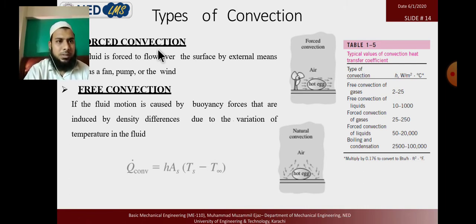Both have different pros and cons. In natural convection flow, we have less energy consumption, because there will be no fan, so the flow of the air is totally free and natural. But in forced convection, the fan is installed in the fridge, which forces air from top to bottom and makes a uniform temperature throughout the fridge, but at the cost of additional electrical energy to run the fan. So both have some advantages and disadvantages.